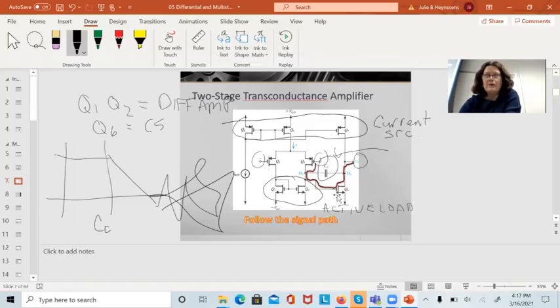The 741 op amp, on some of the older op amps, they used to have 2 pins on the little 8-pin package that were designated so you could put your own compensation cap in. And if your op amp started oscillating, that was your first line of defense, is just stick a cap there. That always works. It's like magic. And then you kill your bandwidth, and then you have to think about what you're doing.